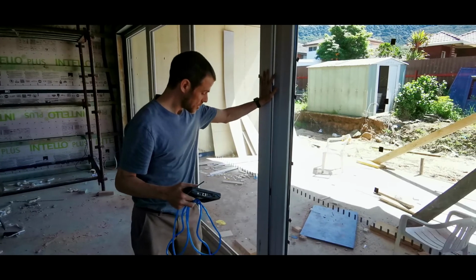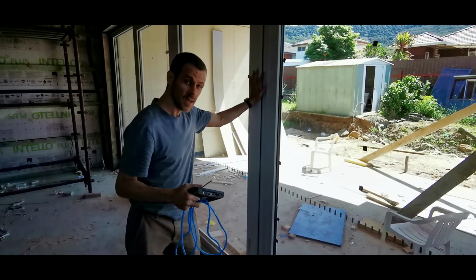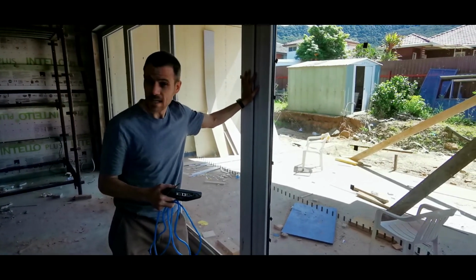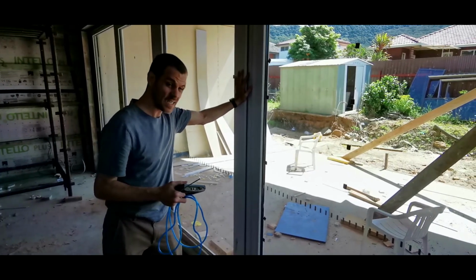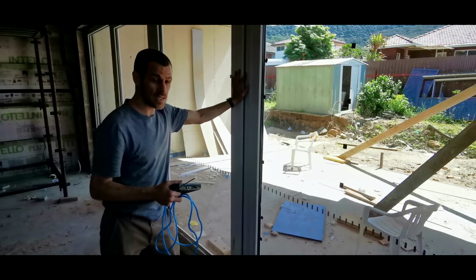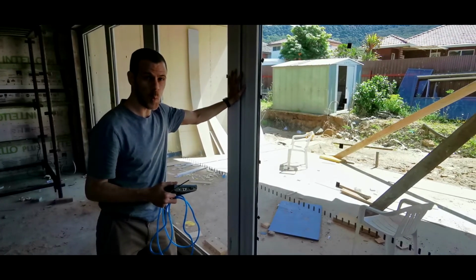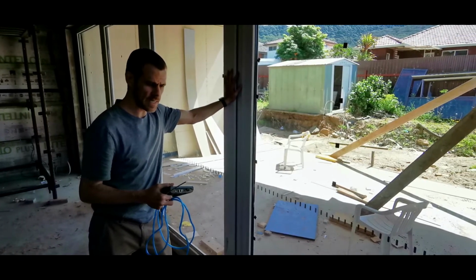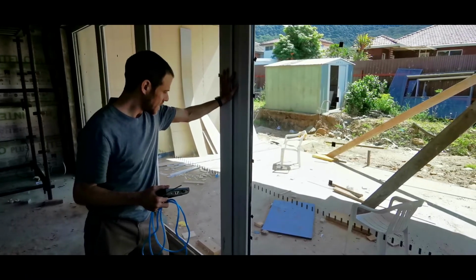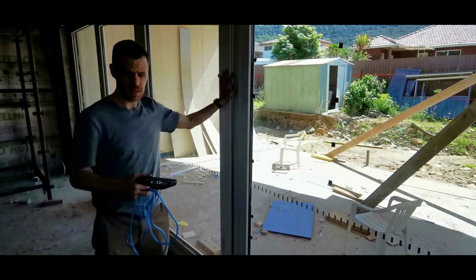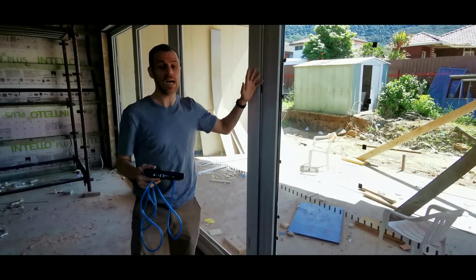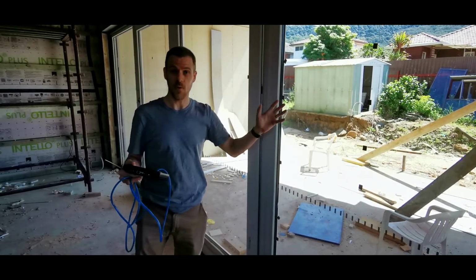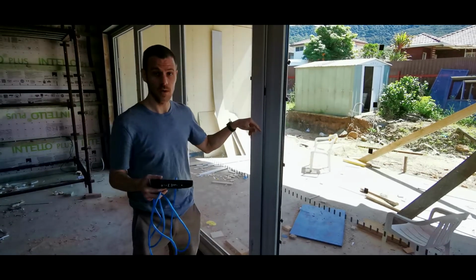Just pushing this door closed causes the pressure in the building to really rise fast and the fan to make an adjustment. And you can hear the building going whistling through all the leaks. If you relieve that pressure by taking this off, the flow goes up by hundreds of cubic meters an hour, which could be the entire leakage budget for a passive house, just from one door.